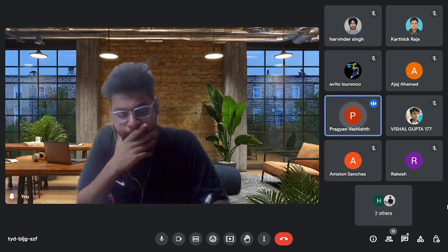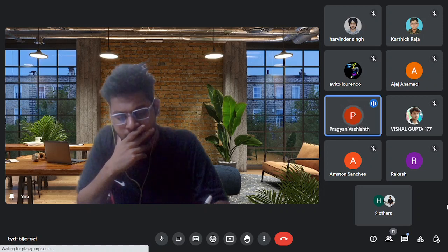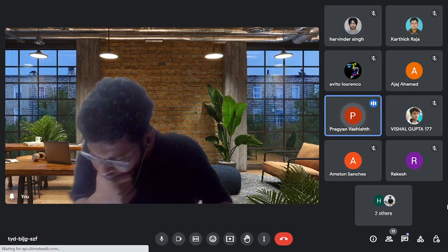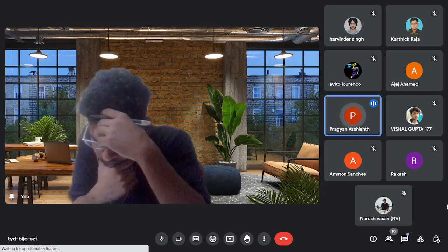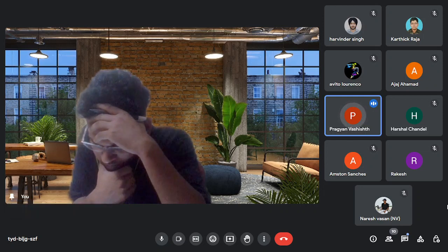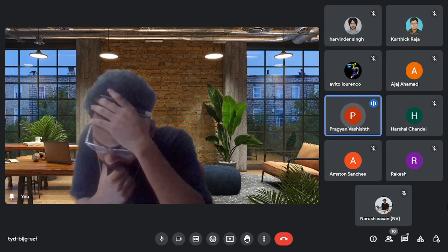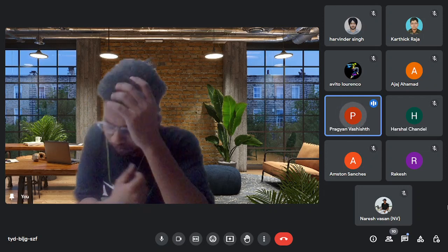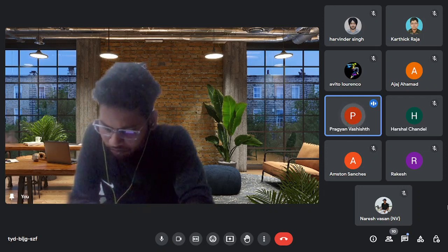Now, the probe will generate high pitched, high frequency sound waves, and the sound waves will travel through the test subject. These sound waves will either reflect at the bottom of the test subject where it is touching the ground, if there are no discontinuities within it. But if there is a crack in between, let's say at a height h above the ground, the sound waves will reflect back from the crack, because sound waves cannot travel through the medium of the crack, that is air.